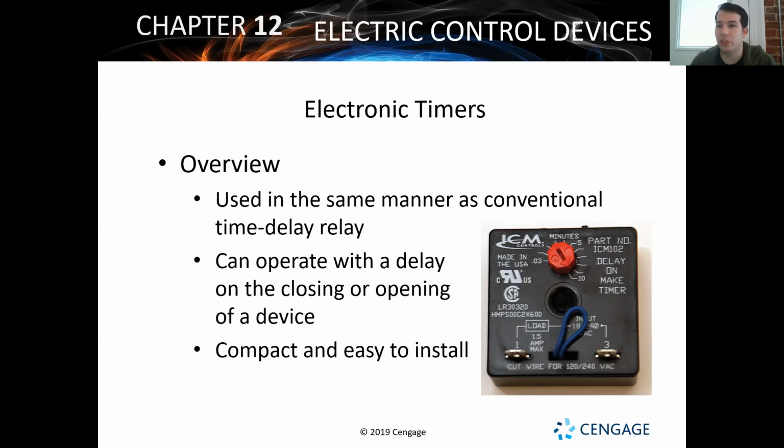So short cycling is when a system is constantly cycling on and off and on and off, back and forth, back and forth. That's what we're talking about with short cycling. Typically it's an issue when the system is trying to fire on again and again, even if there's not a call for cooling or something like that. Putting in a time delay can prevent that system from doing that, and preventing it can help prevent it from damaging itself.